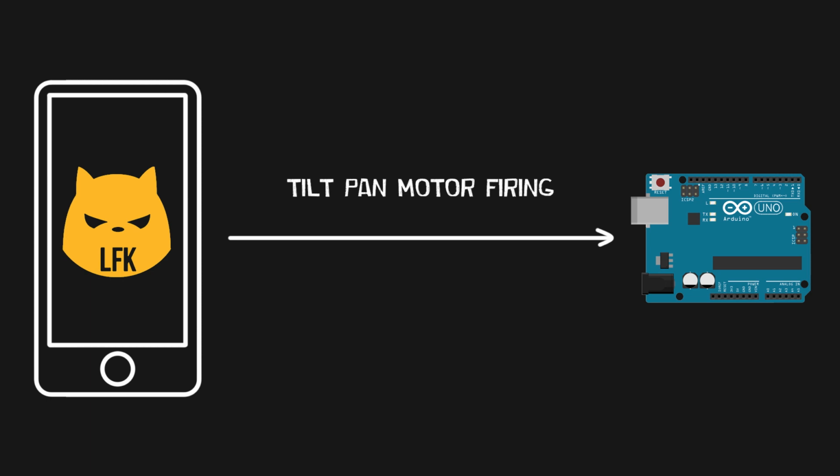We are going to use 254 and 255 since they're 2 bytes that we won't be using for communications, because if you remember, the maximum value we need to send across is 180, so we will be safe. So now the structure of the message we are going to send across will look like this: 254, the tilt position, the pan position, if the motor is on or off, and if the turret needs to be fired or not, and then finish with 255.